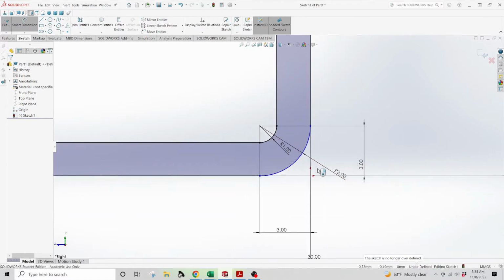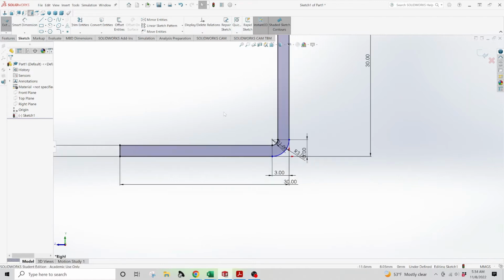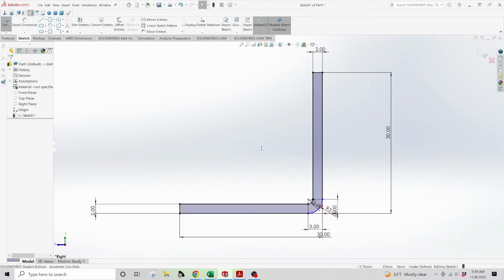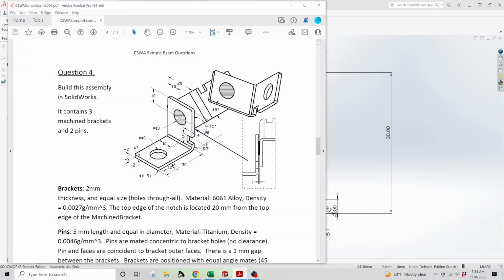So we've already established the point of the origin. We've already established the radius, so there's not a lot else we can do there without breaking some of the other associations. So it's not worth the time to chase something like that. So instead of spending another 15-20 minutes trying to redefine that, we're going to go ahead and extrude as soon as we know extrude to what, 20 millimeters.